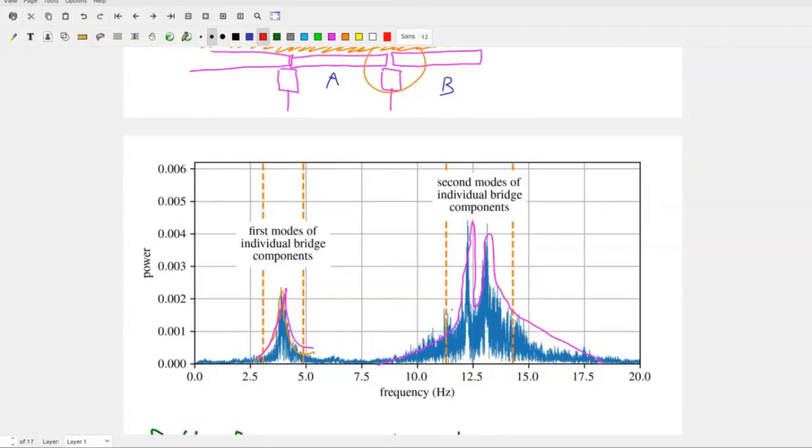So if you think of this bridge, quite dangerous, as a 2-degree of freedom system, right? You have a bunch of first degrees of freedom here, you have a bunch of second degrees of freedom here, but every segment of that bridge oscillates at a combination of the first and the second modes, because they are coupled ordinary differential equations. That's the coupled part, and that is definitely a question on the final. They are coupled through the